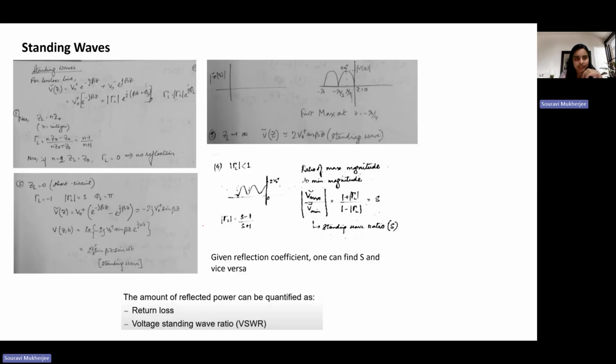Now, because when there's this impedance mismatch, we know that there'll be waves, or voltages, that will get reflected, right? So now you have a forward moving wave and a backward moving wave. And we know from normal understanding that when you have this forward moving and the backward moving wave and they come together under certain conditions, you can have standing waves, right?